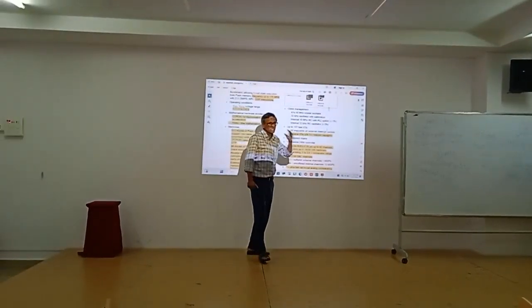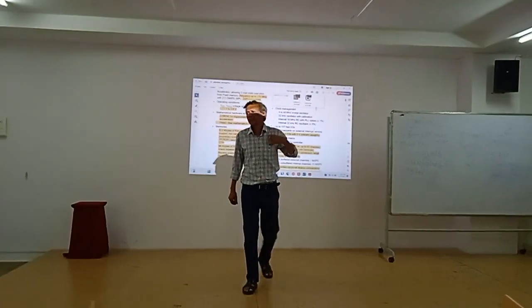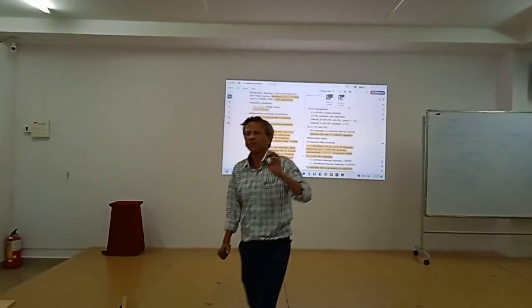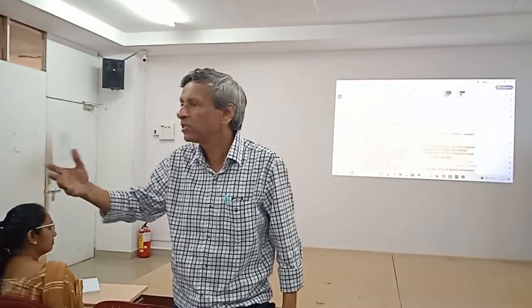Several IOs 5 volt tolerant. Although the microcontroller works at 3.3 volt, but there are many logic ICs which work at 5 volt. So you can directly interface. The controller will not be damaged. That's why few of the pins are 5 volt tolerant.